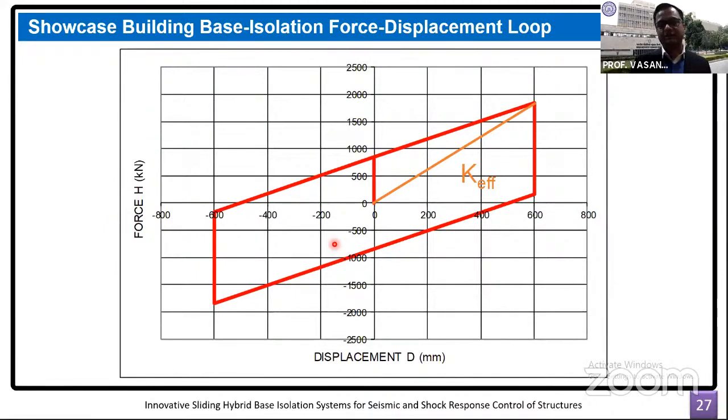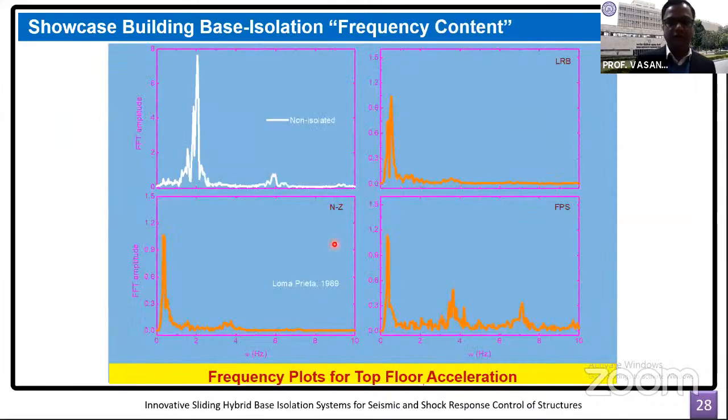But if we conduct some nonlinear time history analysis, of course, we do not get such a smooth and nice curve. So the effect of that linearization is clear, particularly on the isolation systems, as well as the effect of the sliding isolation systems on the contents of the structure, that is, the secondary equipment in the structure, and how they are protected vis-a-vis the counterpart isolation systems based on elastomer.